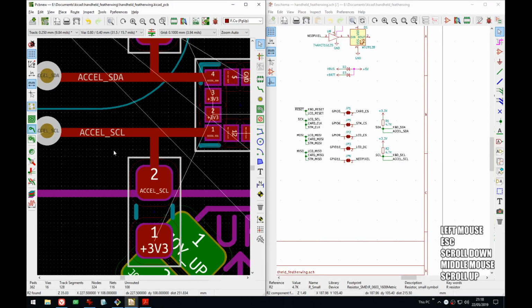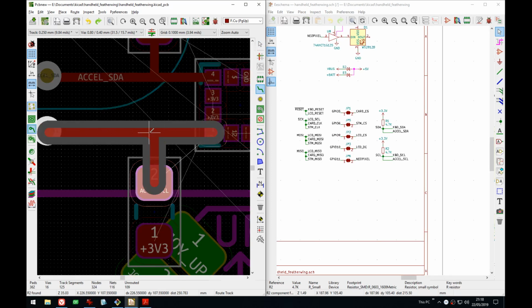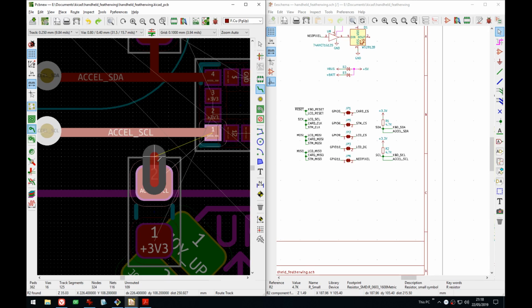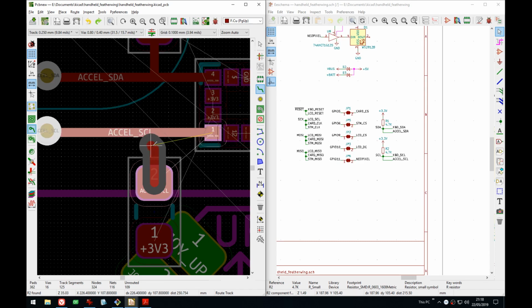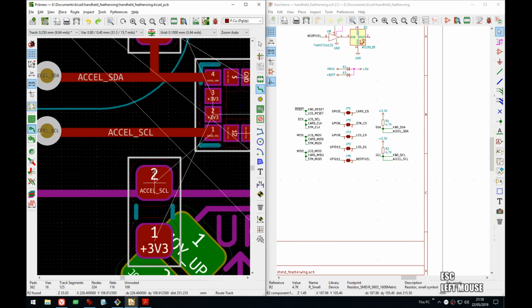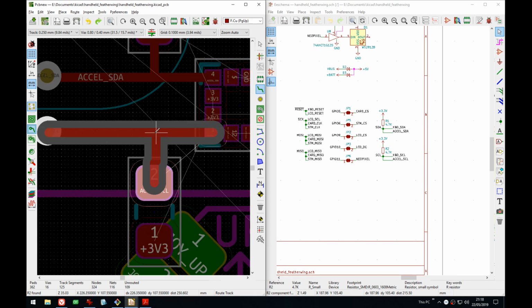Yeah, so what you just saw me do is, because you can see, well, now it wants to, but KiCad was being grumpy and didn't want to have a perfect 90 degrees connection, it was doing something strange to the side. So what I found out is to force KiCad to do this, you just toggle a via, and that will force it to go 90 degrees. Oh, see, now I cannot, but if I do a via, there we go.